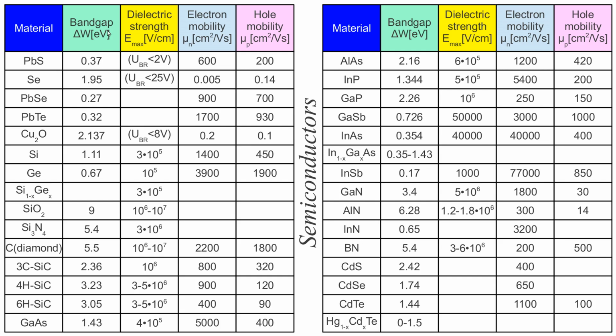The energy band gap between the valence band and the conduction band of a semiconductor is a measure of how our material is going to perform. If the valence and conduction bands overlap, then we have a perfect conductor like a metal. The wider the band gap, the better the insulator the material is. So silicon oxide, which is a very good insulator, has a band gap of 9 electron volts.